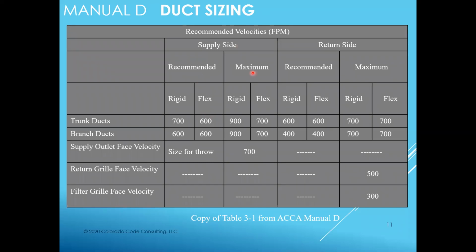And some recommended places and the most you should have. If you stick within the recommended areas when you're designing, you're going to end up with a system that works like it should. Okay, statics are not going to be excessive. The furnace isn't going to sound like it's about to collapse. You don't even hardly hear it run, and you're not going to hear a lot of noise in your rooms.